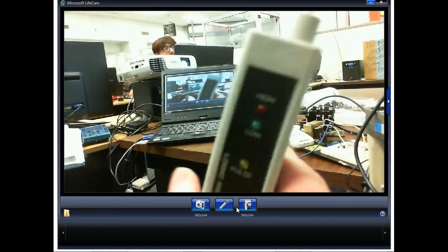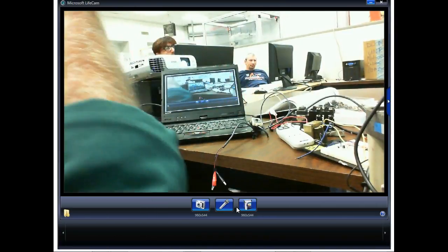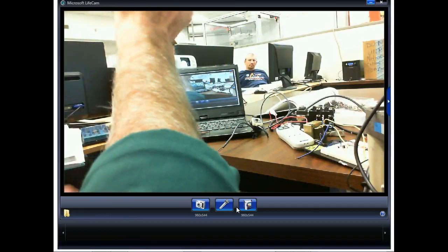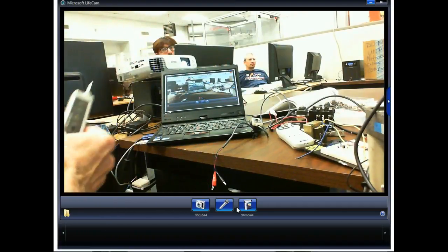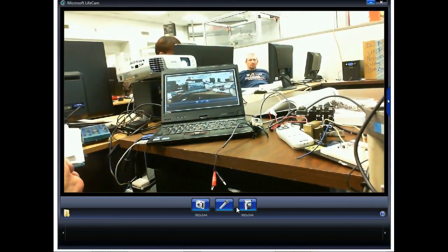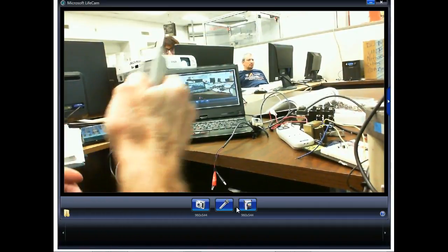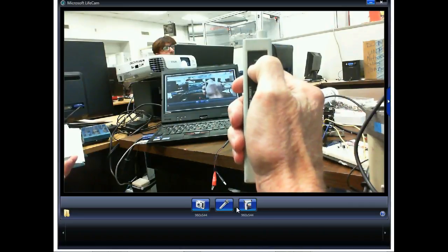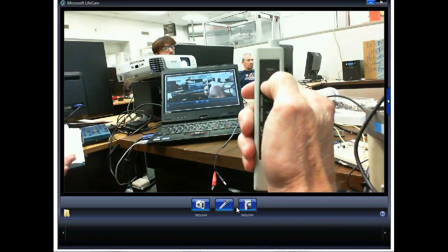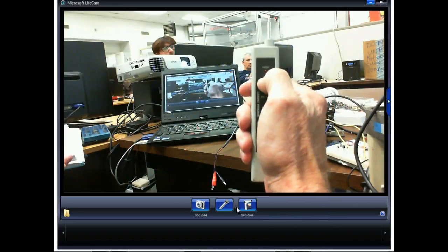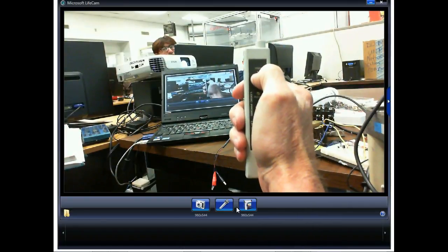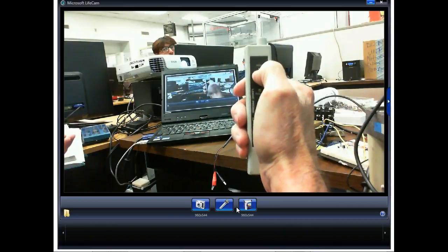High and low. Now these guys here look for legal TTL levels. Because if it's invalid, both the lights will be off. If it sees a legal high, then the red light, this high light, would come on. If it sees a legal low, then on this one the green light would come on. If neither light's on, what does that mean? That means it's invalid. So these are nice little tools.